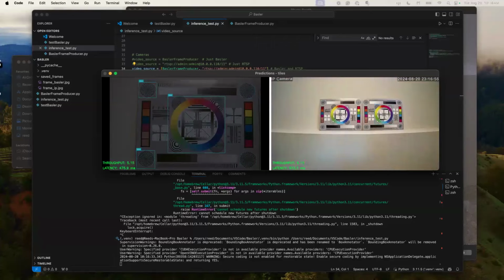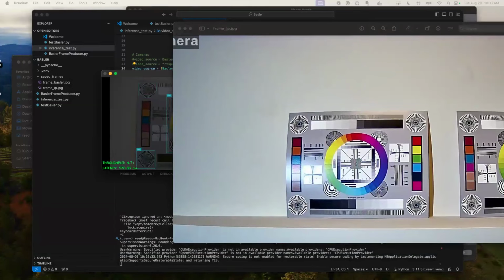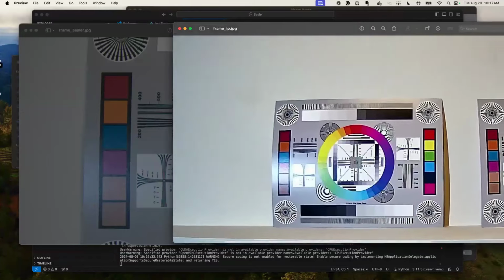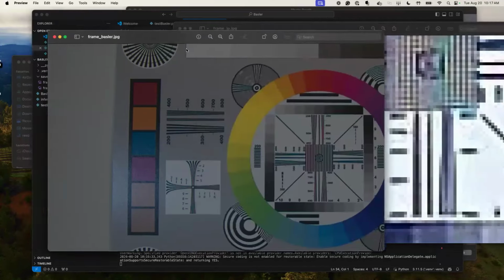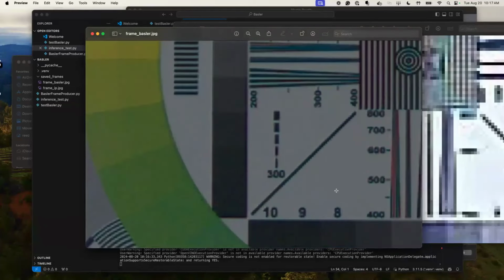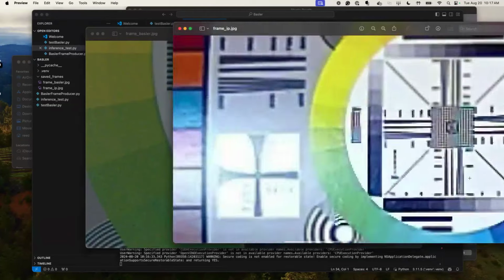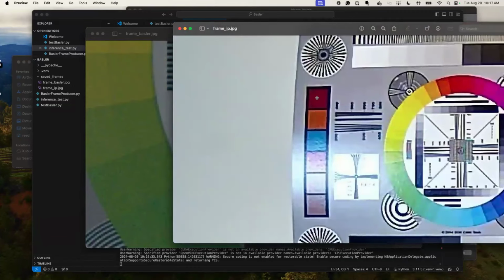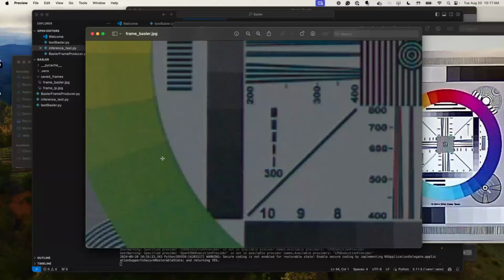Finally, I just wanted to show the difference between this IP camera, where these are still frames I captured earlier, and the machine vision camera. If I wanted to read the text on this board over here, if I zoom in, these are actually letters and numbers, but I can't read any of that. The resolution is very poor. But if I go over to this machine vision camera and zoom in, I can read these pretty well. So this is going to enable things like OCR, optical character recognition. I can actually read these numbers if I want. This is when you'd go the extra mile to get the more expensive camera, when you want to detect smaller, finer things. With an IP camera, if I just want to detect this square up here and see if it's red, that's probably fine. But in certain scenarios, if you want to read characters or stuff like that, it's not going to be a really good option for you.